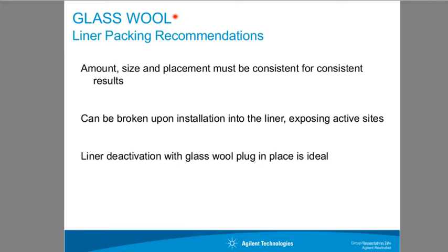With the glass wool, this has been an issue going back and forth, I wouldn't say an argument, but glass wool can be problematic. If you pack your own liners, there's a lot greater chance of it being problematic, in part because the amount, size, and placement need to be consistent so you have consistent results. If in one instance you have a really densely packed amount of glass wool, you can change the restriction in the inlet and slow the flow rate through your column, and you can actually have retention time shifts just due to your liner and specifically the glass wool in there.